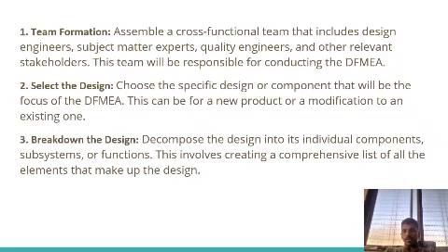Select the product design. Choose the specific design or component that will be the focus of the DFMEA. This can be for a new product or a modification to an existing one. Break down the design. Decompose the design into its individual components, subsystems, and functions. This involves creating a comprehensive list of all the elements that make up the design.